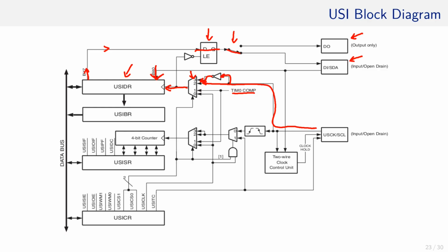That is useful in case I have a protocol which does not have a clock, such as UART. I just have to set the timer such that there is a compare match for the desired baud rate, similar to what we did in the first part of this chapter. There we set the duration to 6.67 microseconds to mimic the one-wire protocol using the UART interface.